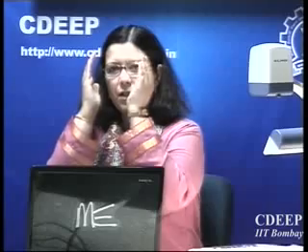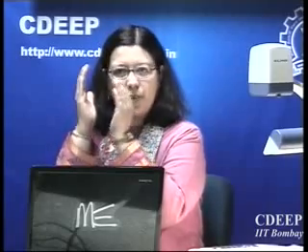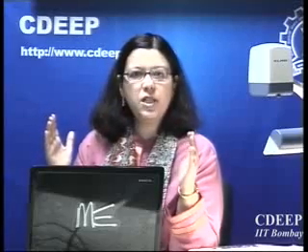The difference between two consecutive frequencies in FFT, which is 2 pi by M, is called the bin. M is the M-point FFT. I don't say N because it would get confused with the number of bits. So the frequency bin also improves, which means you will have better resolution in the frequency domain. But that means you need to increase the number of samples for a given interval. If you have a data acquisition card, you need to put a lot of memory on the card so that you can collect many samples.